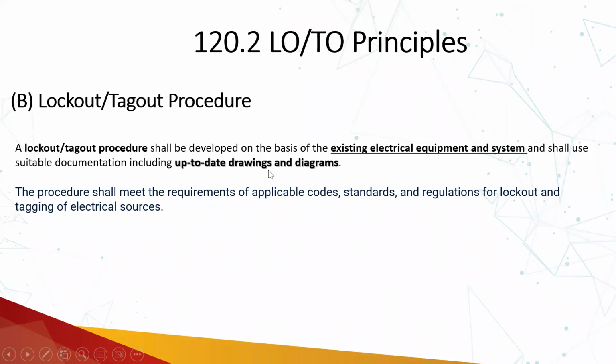So normally when I was working in the operation department, early morning we used to have a number of shutdowns for transformer change, shutdowns for providing new connections, meter change, etc. All those shutdown procedures used to be written based on the existing single line diagram, and we were very much dependent on those single line diagrams, and we needed to make sure that they were up to date, because normally in distribution companies the situation changes more frequently.